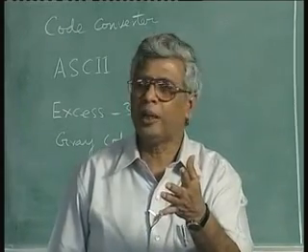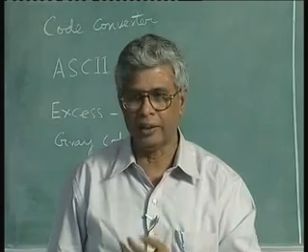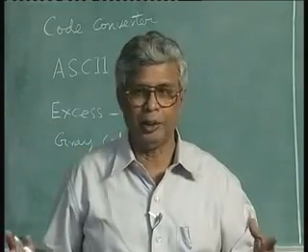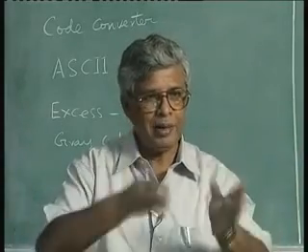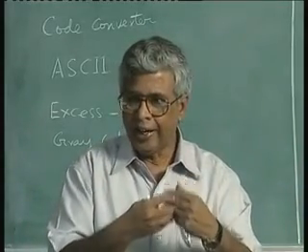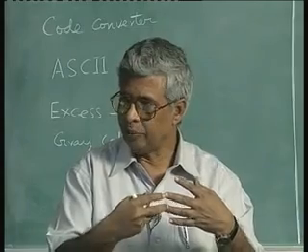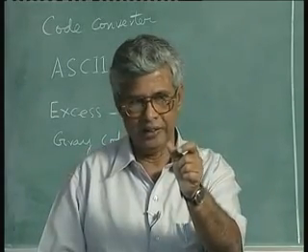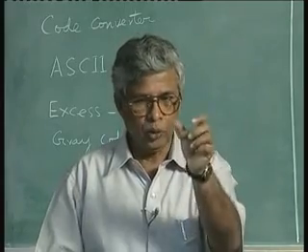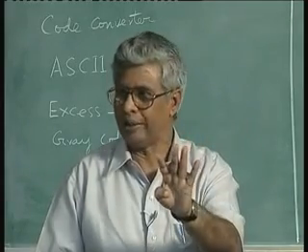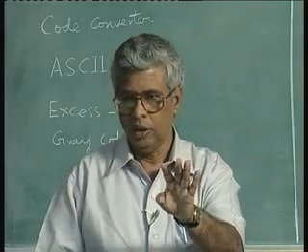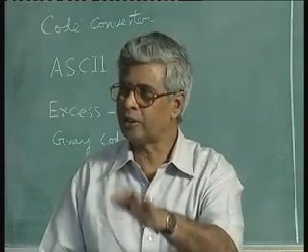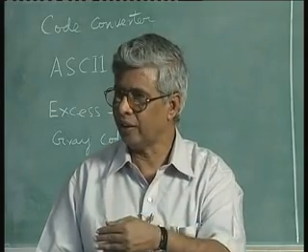There are two ways of handling decimal numbers in a computer or in a calculator. I can convert the whole number into binary and have a series of ones and zeros, which is mind boggling. Or I can take digit by digit, convert them into binary and work on each individual digit and put them together finally. When I consider each decimal digit as one unit, each of those units will have 4 binary bits, right? Out of 4 bits I can have 16 combinations, but we are only interested in 10 combinations, 0 to 9. The other 6 are not used.